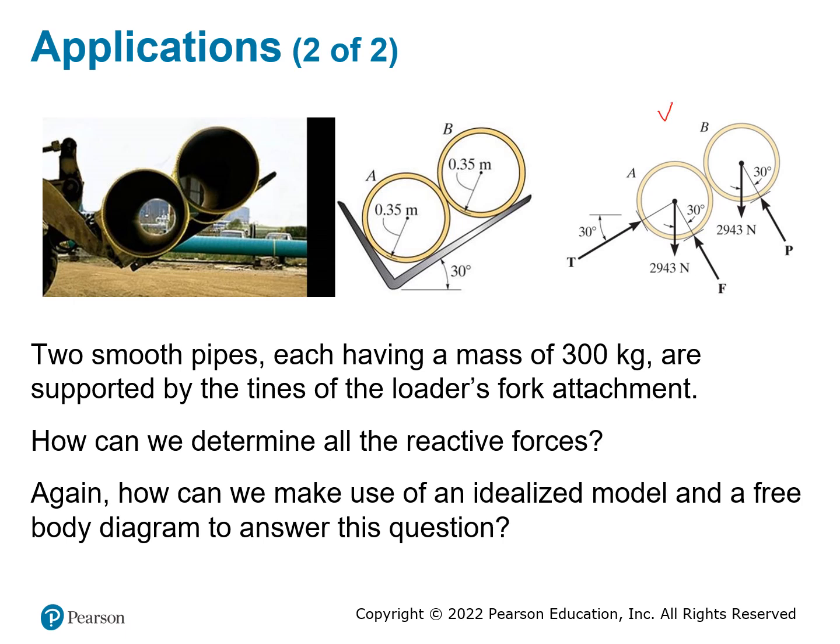So here, the free body diagram shows both pipes. You have the reaction forces F here and P here. Both of these come from the bottom because you remove this L-shaped support. You also have a T force here, which is another support. Are there any supporting forces here?